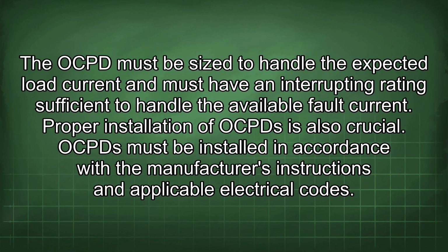The OCPD must be sized to handle the expected load current and must have an interrupting rating sufficient to handle the available fault current. Proper installation of OCPDs is also crucial. OCPDs must be installed in accordance with the manufacturer's instructions and applicable electrical codes.